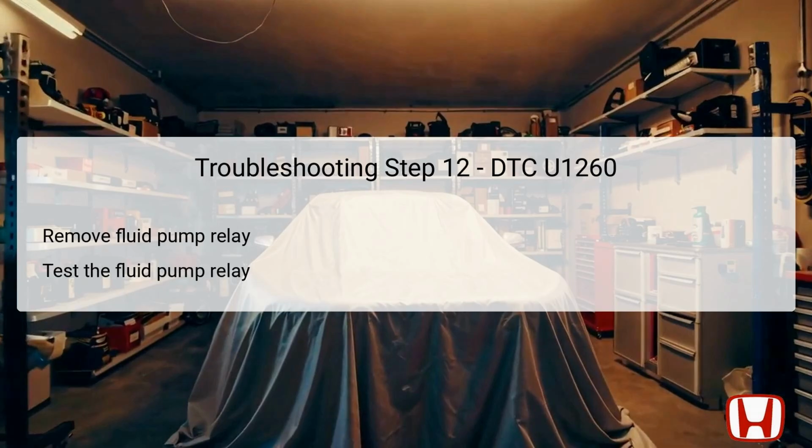In case the relay is functioning properly, the next steps will hinge on evaluating wiring or additional components in the system that may be causing inconsistencies in pump activation. Relays play a crucial role in ensuring the auxiliary transmission fluid pump receives power when needed, so validating their condition is pivotal. Step 13 transitions to checking the +B EOP line, which plays a critical role in ensuring the auxiliary transmission fluid pump receives adequate power.